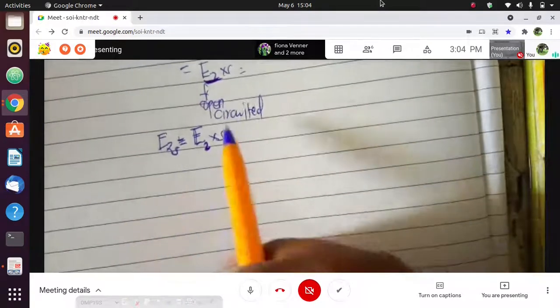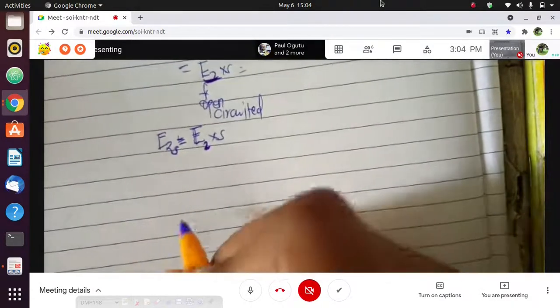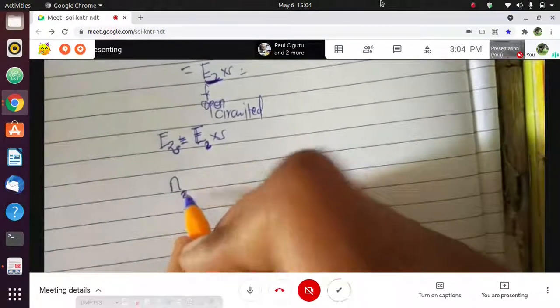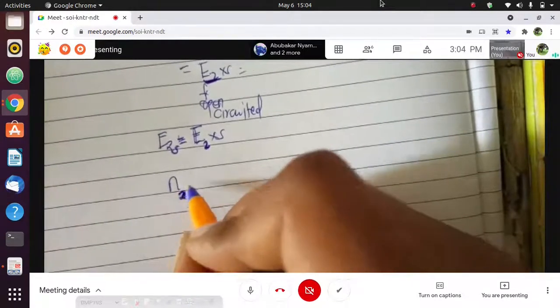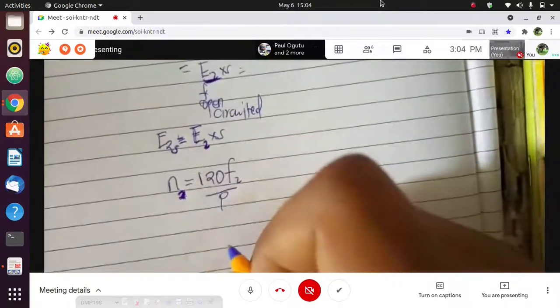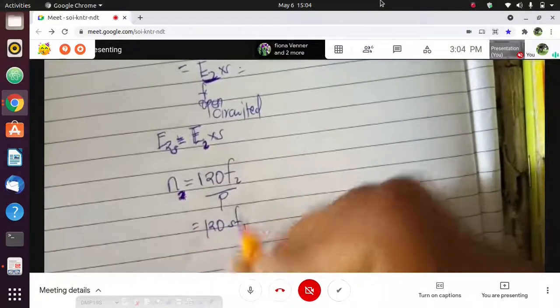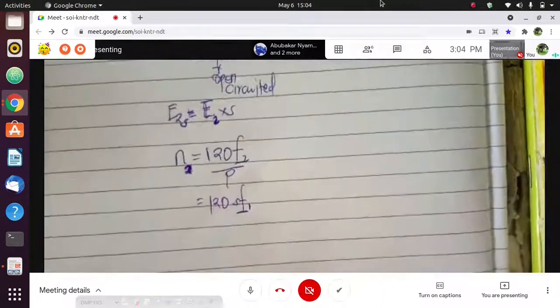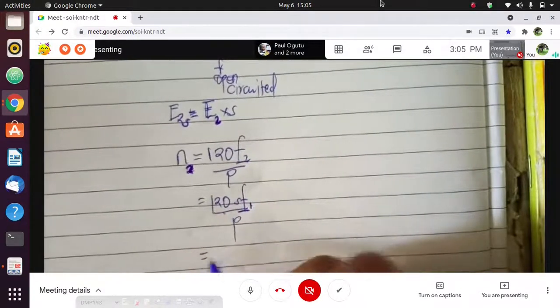So the induced currents in the three-phase rotor winding will produce a rotating field, and the speed of that rotating field, n2, with respect to the rotor, will be given by 120 f2 divided by p. This is 120 times s f1 divided by p. Remember, f2 is slip times the stator frequency. This gives you s and n_s.